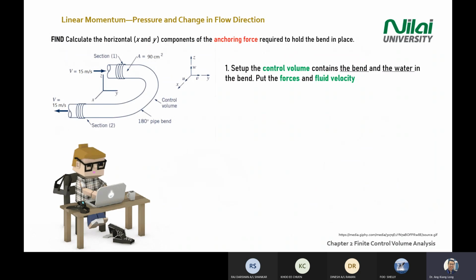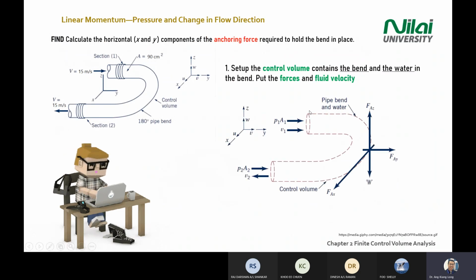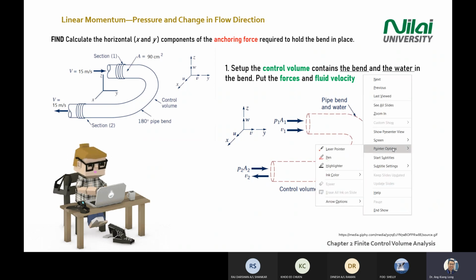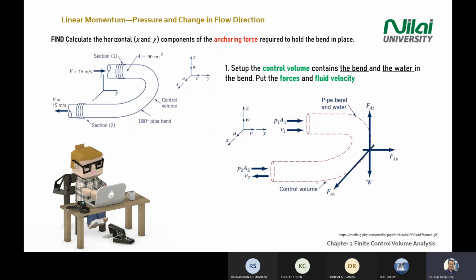The first step is to draw the control volume diagram, like what you see on the screen here. In the test or final exam, it's going to take you maybe 5 to 10 minutes just to draft the diagram. So again, I repeat the SOP, the steps. First, control volume. You trace the shape that you see in the solid line here, and then draw the control volume. After that, label your input and output, in, out.